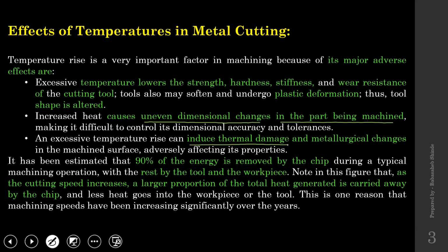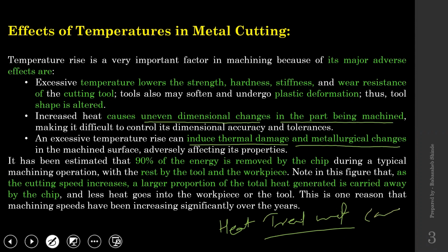induce thermal damage and metallurgical changes. Now for this one, you need to go to metallurgy and think of the heat treatment processes. So when you heat material above the critical point, above the recrystallization point, and then you cool it, either rapidly or slowly, whenever the material undergoes this heating and cooling cycle, there will be certain microstructural changes.